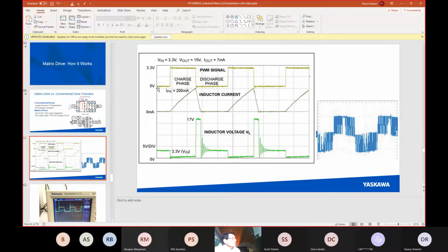with our pulses. This is the charge pulse coming off the DC bus. I apply it to one phase of the motor, and here's what happens in the motor as far as current is concerned. I get a rising current. Why do I not get a similar shaped current as the voltage? And that is because the motor has inductive reactance. An inductor is a current shock absorber, the same way a capacitor is a voltage shock absorber.